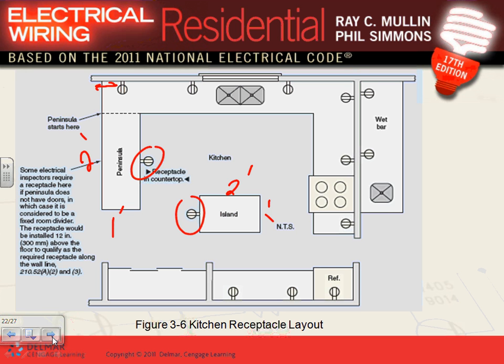Here's your 2 feet, here's your 4 feet, 2 feet again, 2 feet, 4 feet, 4 feet, 2 feet, and this one, if it's a foot or more, you need a receptacle. Any question, guys, about this?